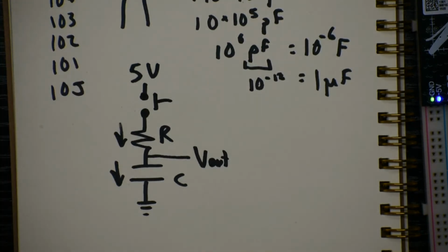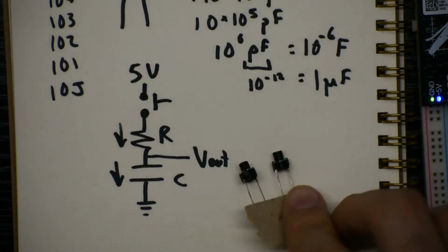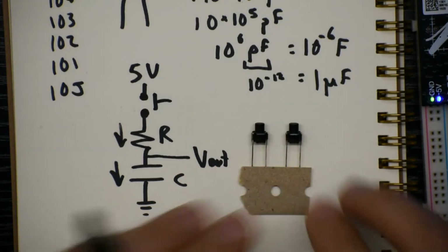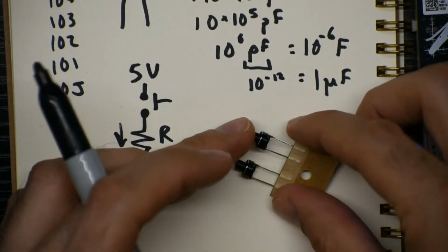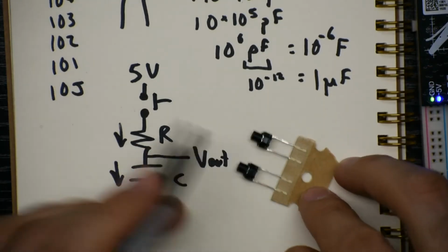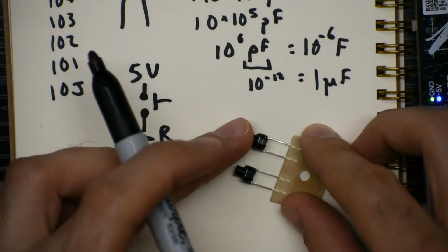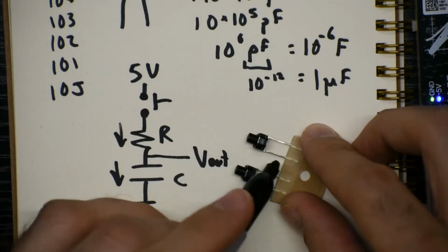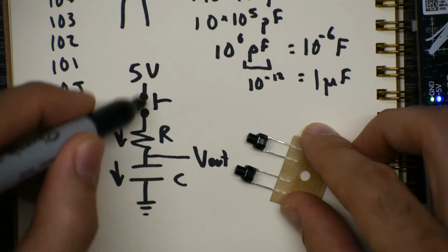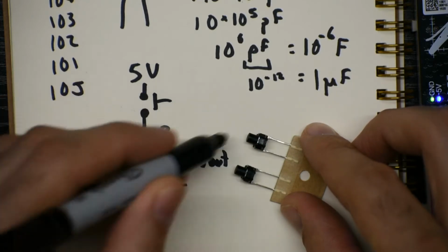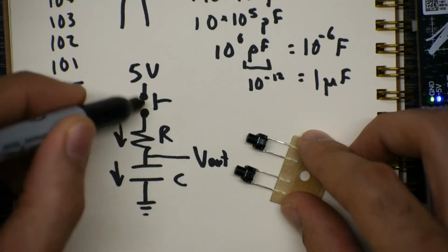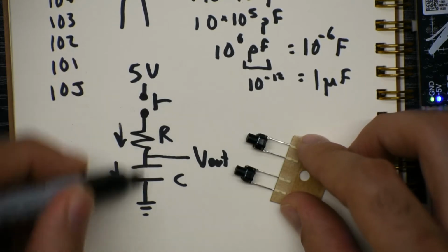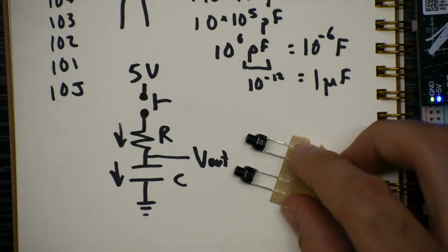In your kit, we've got some buttons. Find those. Here are some push buttons. I've got 2 also embedded in a piece of tape, and you can push them. This is essentially a wire that's broken, and when you push the plunger, it makes the connection between the 2 wires, making a connected wire. So when we're not pushing the button, this wire here is not connected to 5. When you push the button, it is connected to 5. That means current can flow this way, charging the capacitor.